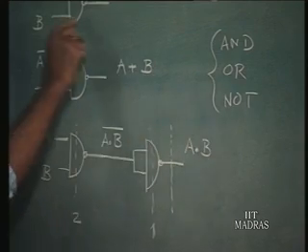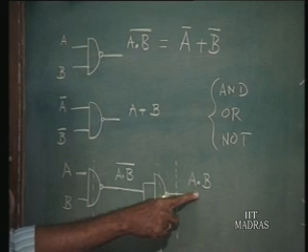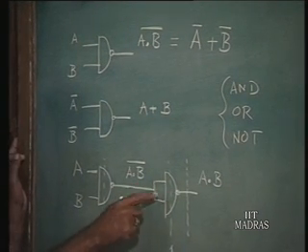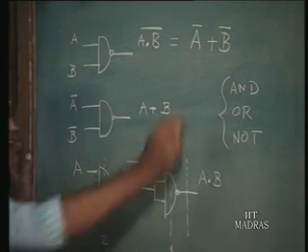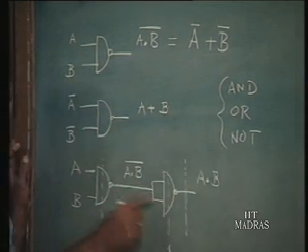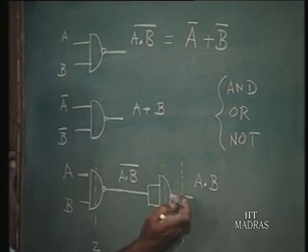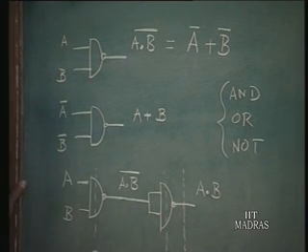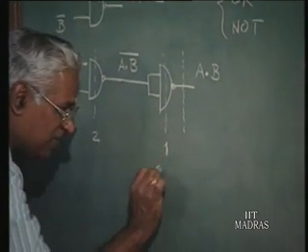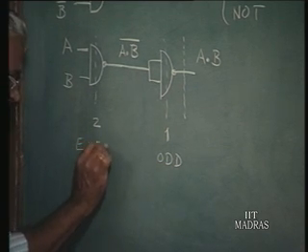Now, we see that the NAND gate performs as an OR gate or as an AND gate, and when the input to the NAND gate is shorted, it just works like a NOT gate. So, a NAND gate itself can perform as an AND or OR or NOT depending on what level it is in. Suppose you want a function, see at what level it is: level 1, level 2, level 3, level 4. Without much discussion, I can just extend this, the level 1 as an odd level and level 2 as an even level. You can work it out.